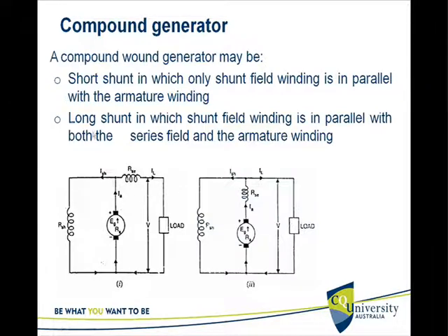If it is called long shunt, the shunt field winding is in parallel with both the series field and the armature winding. The series field and the armature winding are in parallel with the shunt field. That's called long shunt. Short shunt and long shunt.